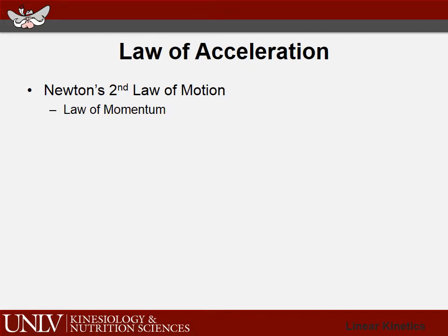So let's move on to the law of acceleration, which is Newton's second law. Now I've also put here law of momentum, and why I put that is because if you look at physics textbooks, and you take the physics class, the original creation of Newton's second law was in momentum terms. And I'll show you in a moment how that is derived, but essentially the law of acceleration deals with F equals ma. Now what you're going to see is this epsilon here, and this is a summation of forces. So that is all the forces that are acting on the system.